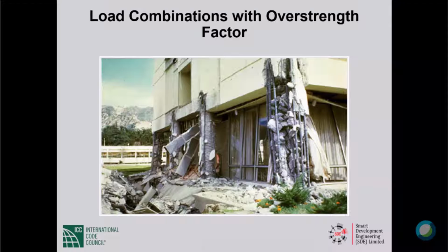This is a by now famous picture. This was the Olive View Memorial Hospital after the 1971 San Fernando earthquake. You see the bottom story has columns, and then the shear walls start. Those columns, back in those days, when there was no difference between a California column and a Chicago column, had plenty of longitudinal reinforcement, hardly any transverse reinforcement. Tie spacing was 12 or 14 inches, no 135-degree hooks, no cross ties. The building is standing up only because, for reasons unknown to me, those central columns are spirally reinforced columns and the pitch of the spiral is very tight. So those columns are in good shape, except the cover has fallen and they are holding the building up. If all the columns were like that, the building would have been down on the ground.